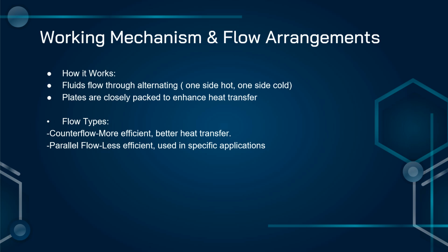Many of the most popular types of heat exchangers used in the mechanical industry consist of shell and tube, air-cooled, plate and frame. Many plate heat exchangers are made of corrugated plates on a frame. This creates high turbulence and high wall shear stress, resulting in a high heat transfer and a high fouling resistance.